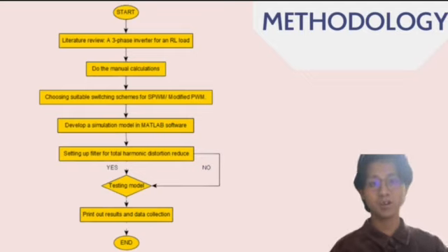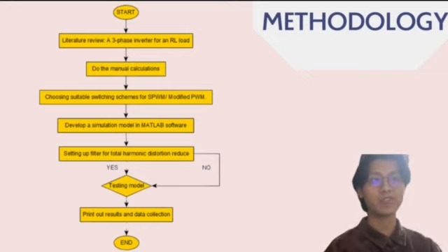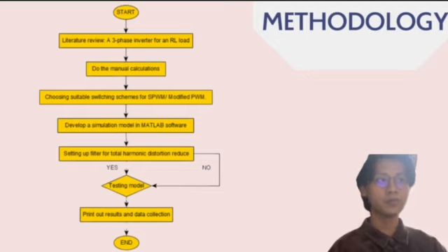From figure 3.1, it shows the whole process to successfully complete this project. The first step is to construct the model. Students need to brainstorm ideas by doing primary research about the project and the question given. Secondly, in this project, the data can be related to the 3-phase inverter with RL load, through the data given that consists of input voltage, line-to-line voltage, frequency, and others. The value of the harmonic distortion can be calculated manually and must be less than 7%.